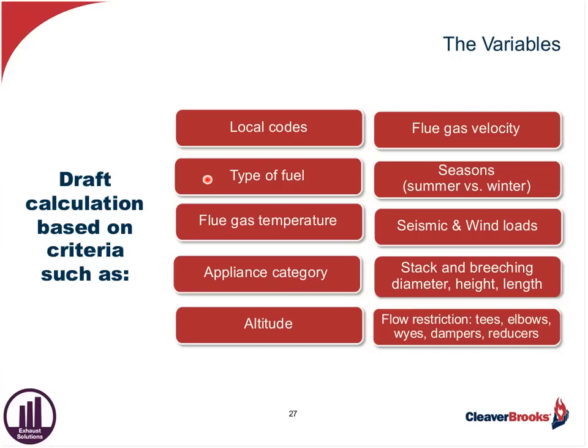So you could have a boiler that's operating at 100 pounds pressure, which is 338 degrees, but you still could get into a situation if that breeching and stack has not been properly designed, where even though you're coming out of that stack at, say, close to 400 degrees, by the time it gets to the stack, it could be down to dew point. And that becomes very, very important. And of course, if you've got an oil fuel, that dew point's even higher. You're talking 235, 240 degrees with number 2 oil. So that becomes a huge consideration, the type of fuel I'll be burning.